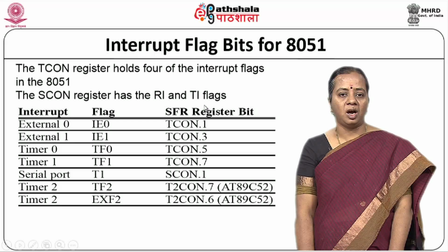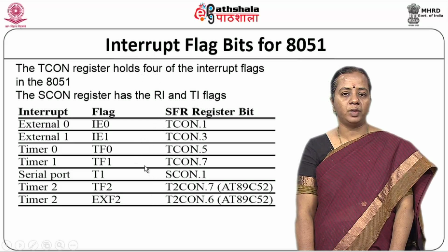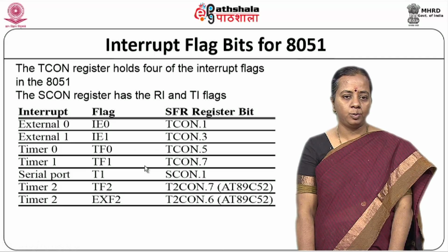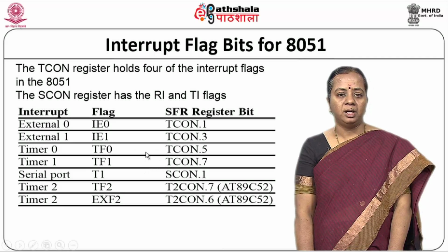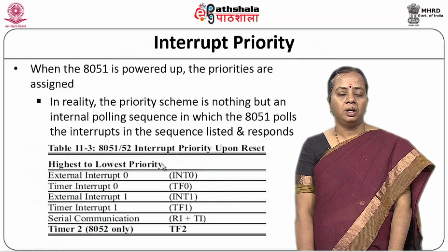And the SCON register, the RI and TI flags, the TCON register, all these interrupt flags are very important. Sometimes these have to be cleared by us, like TI and RI, while the TF0 and others will be cleared by the hardware itself.